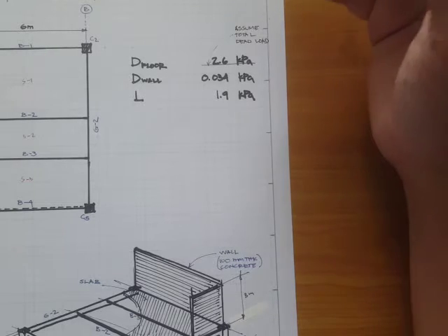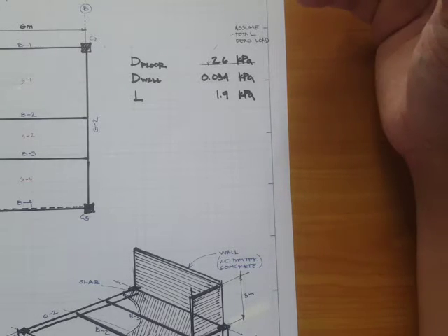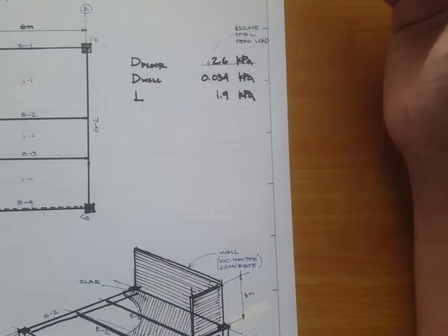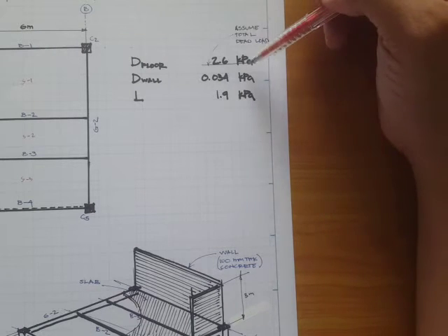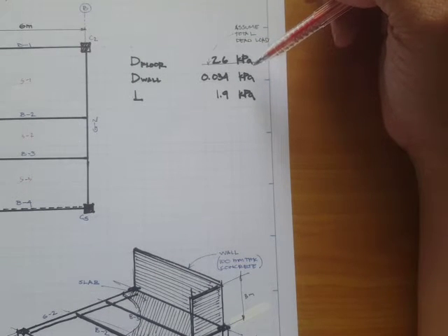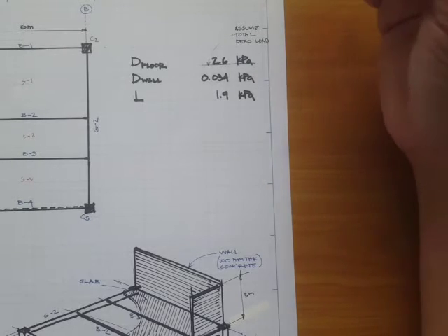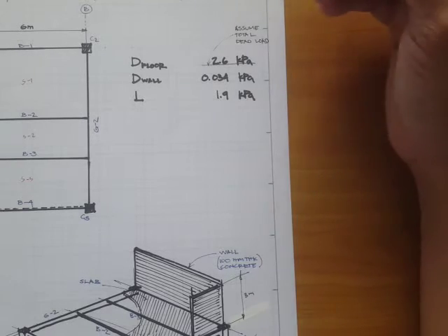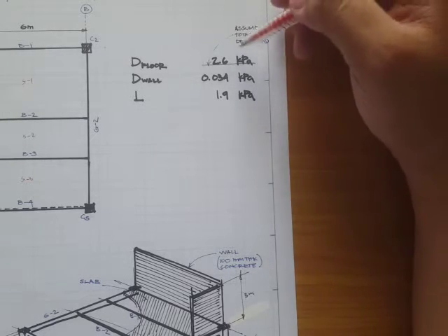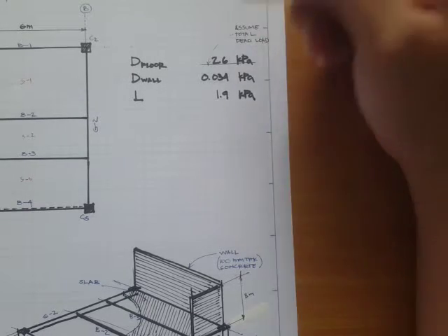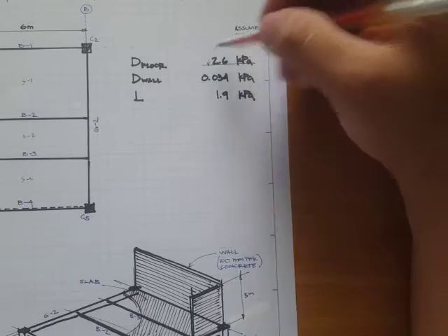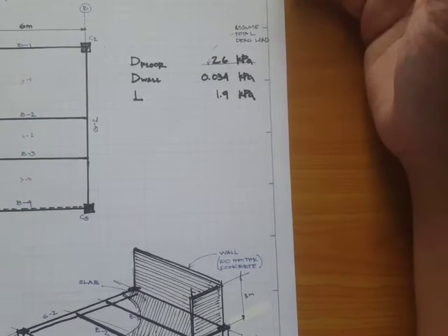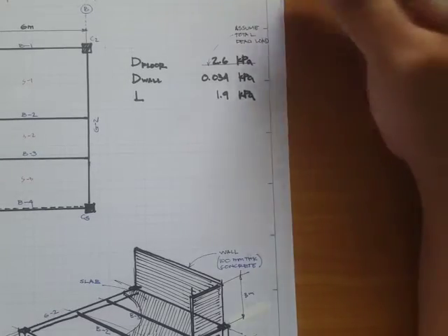Later on you'll encounter terms like superimposed dead loads, meaning that other than the dead weight of the structural members itself, there are still dead loads, like for example the ceilings or the electrical service, and if there are plumbings or pipings and stuff like that, then there's another value you have to add to the dead weight of the structure. For now let's just assume that this is the total dead load.